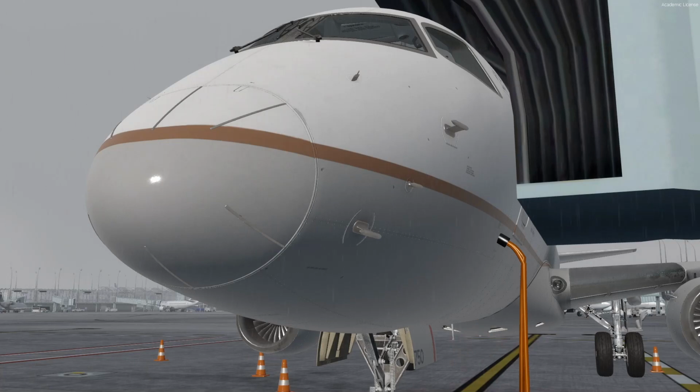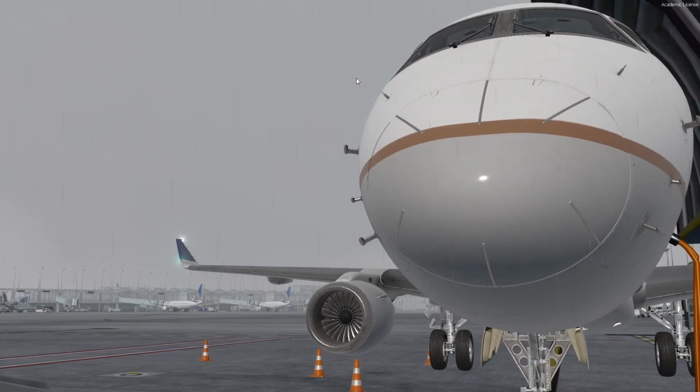The airplane has two ice detectors on the nose section. They're basically small pieces of metal that would be the first thing to accumulate ice if we were to accumulate some. You can see it right here. This is the ice detector, not to be confused with the true air temperature probe and the air data probe, the smart air data probe. So those are the smart data probes. This is the true air temperature. These are the ice detectors. So we have one on each side, like so.